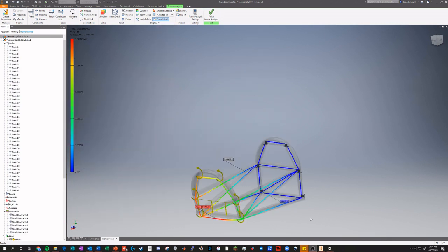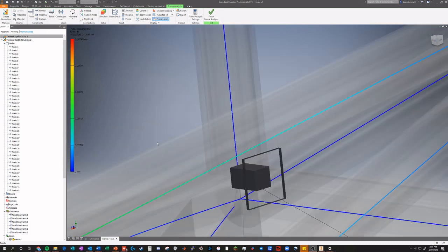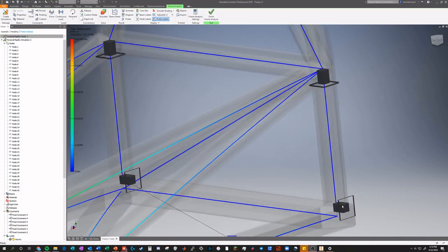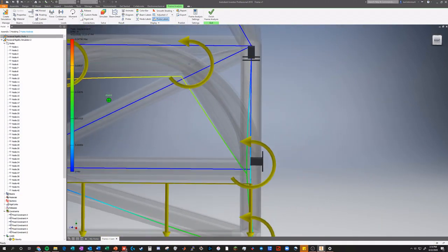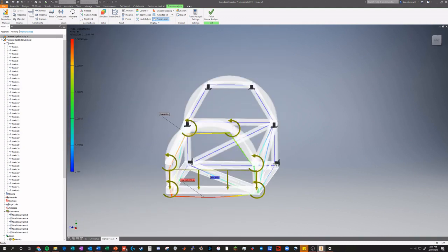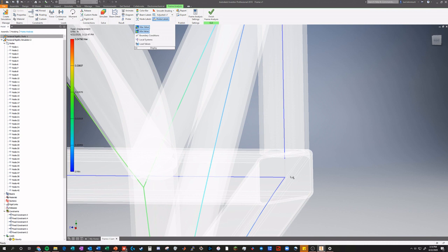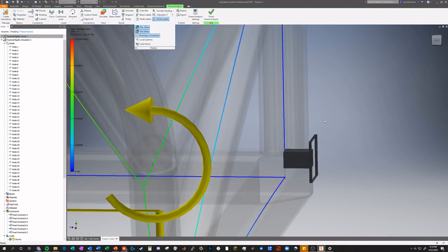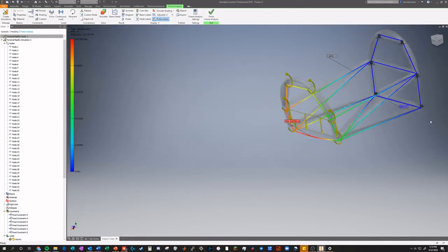All right, just a quick note here. I was able to get all these constraints to work. What I ended up doing is I just clicked the nodes. Basically what happens is when you trim these beams, it actually will trim them down. And so you can see that blue line doesn't extend all the way down into the node there. But it joins them all into one big node, basically. It kind of treats them as one big node within the beam model.